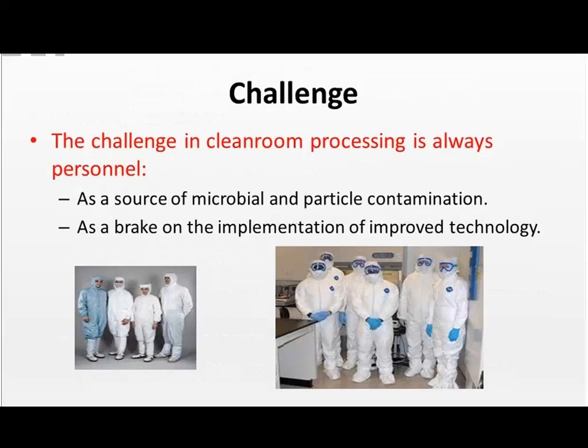The challenge for setting up and maintaining clean rooms is always personnel. They are the largest source of contamination in our clean rooms. We sometimes think of equipment as being the largest source, but it's not. It's our personnel. Personnel not only bring in microbial bioburden, they also bring in particulate contamination.